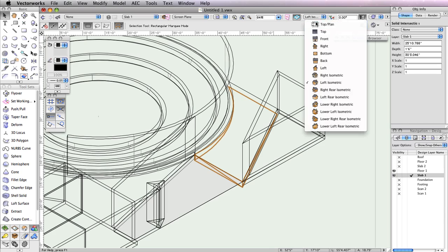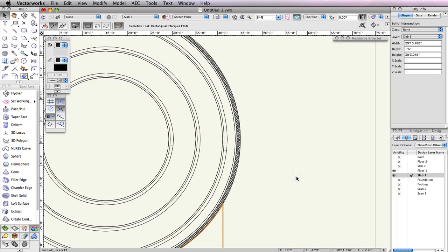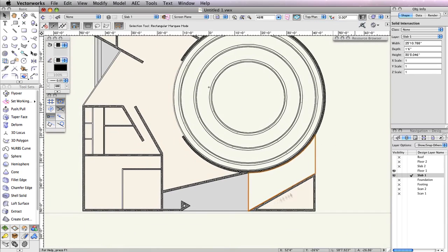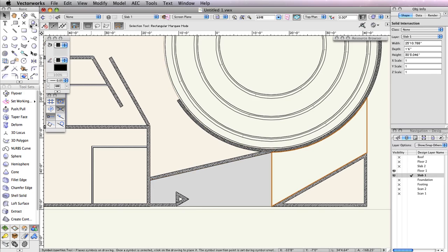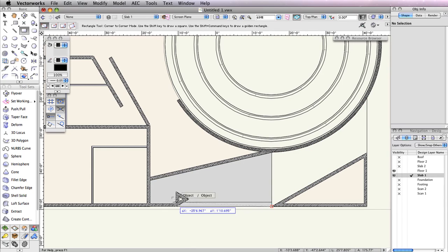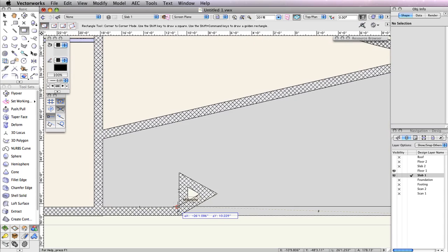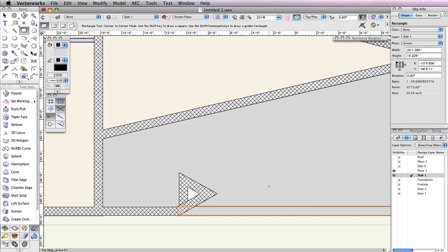Before you extrude the polygon, select the Rectangle tool from the basic tool palette to draw the steps for this pad. Also, make sure the first mode is enabled in the toolbar. After activating the tool, click the bottom right corner of the polygon. Then move your cursor to the left and snap to the inside of the corner of the bottommost wall to create